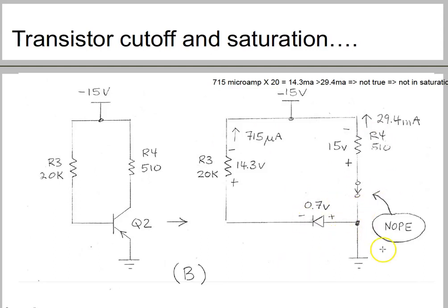That's not happening here. The currents are non-zero, and neither are they in saturation mode. You might be tempted to conclude that when Q2 is not saturated, it must be in cutoff mode, but that's not true, because for cutoff mode the current should be zero. There are actually three transistor states: saturated, cutoff, and the third one is called neither, which means linear.